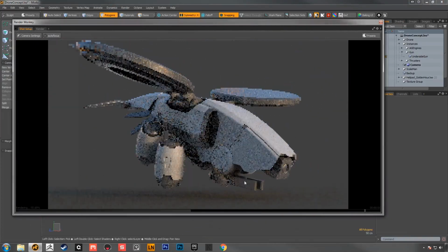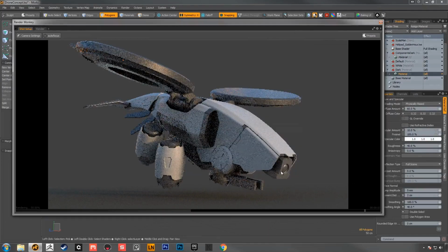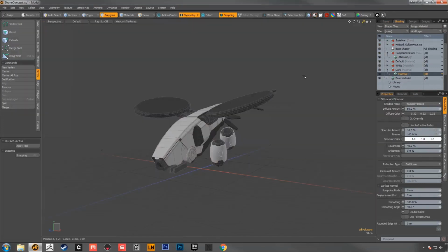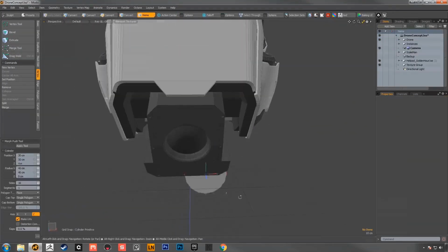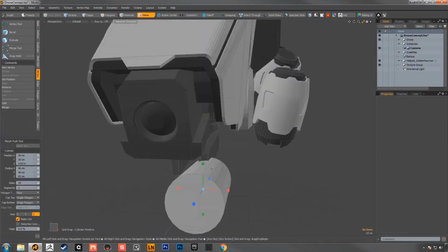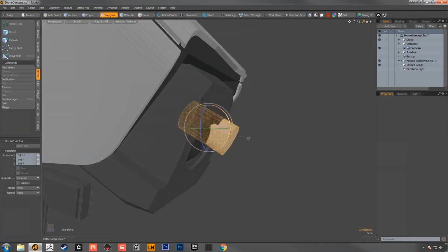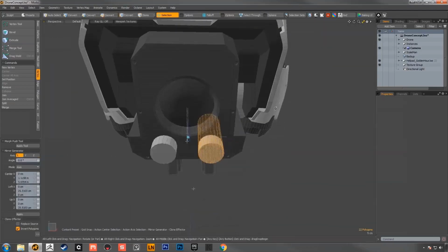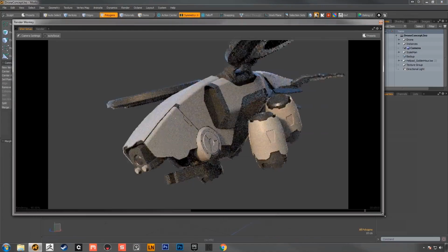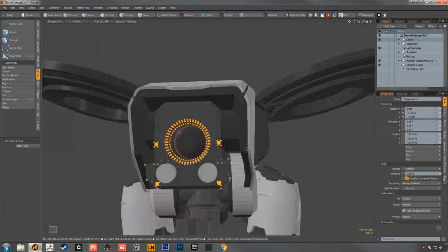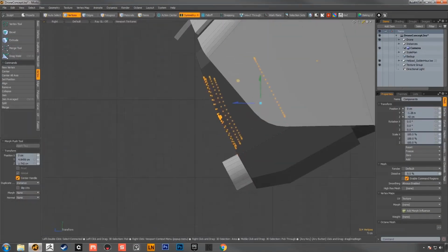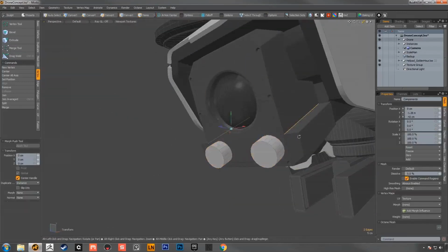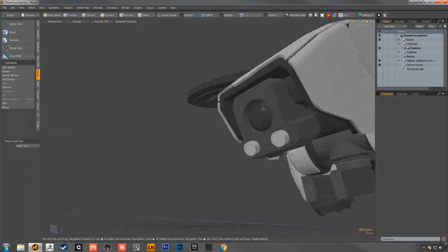I'm also, you probably noticed, I didn't do any control loops or any extra bevels around the edges of those holes, because that's where I'll use the round edge shader and I'll bake that in. So my high poly is basically a mid poly with a round edge shader, and then I'll bake all of that down to the low poly. So elements like my camera, my gun, maybe some of the smaller elements like parts that deflect energy away from the jet boosters and stuff, those will be baked. And the reason why I want to bake those is because I want them to have small details.